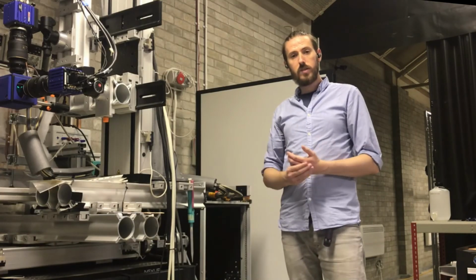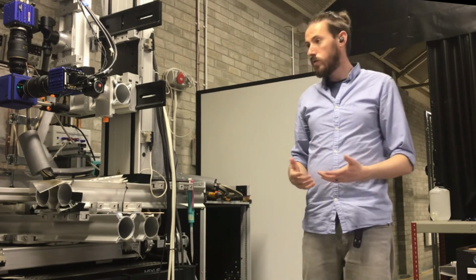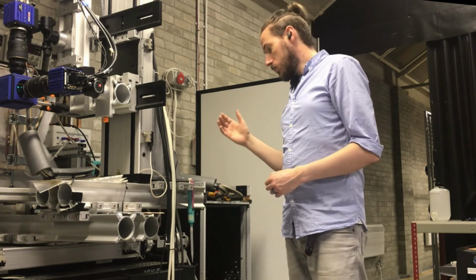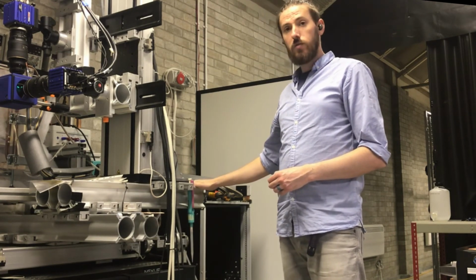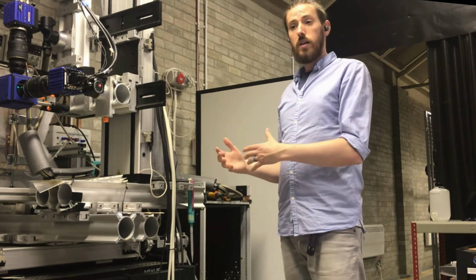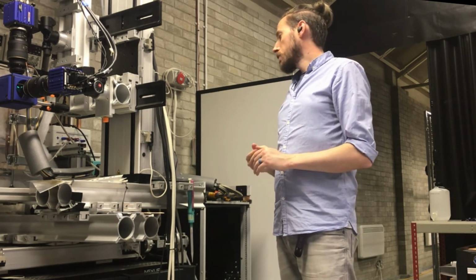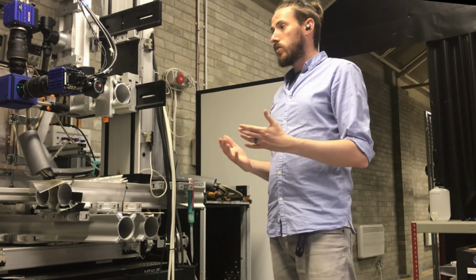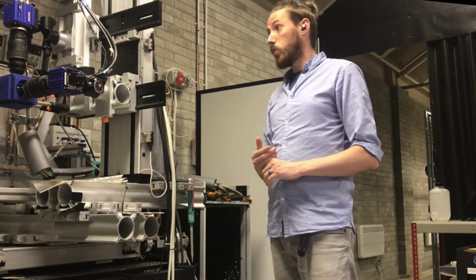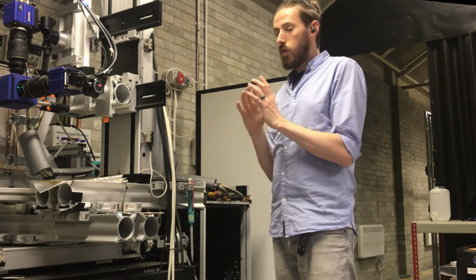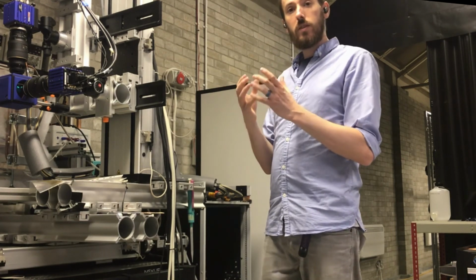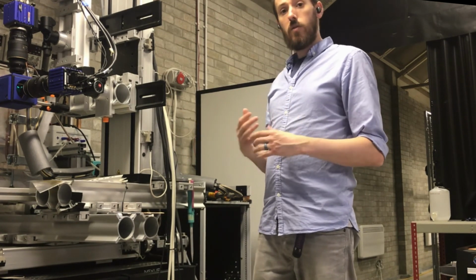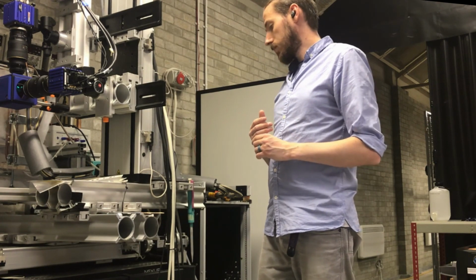Okay, so the system has now been drained down, cleaned out and disassembled. It should be that if anyone reintroduces using the translation stages in future, there's no collisions likely, which was a worry before, and it will require some amount of assembly before it can be used again, but it's now ready to either be disposed of or to be put into storage. And what that really means is putting caps over anything that's dangerous in terms of like the laser, but also protecting lenses and things from dirt ingress and dust buildup and stuff like that.